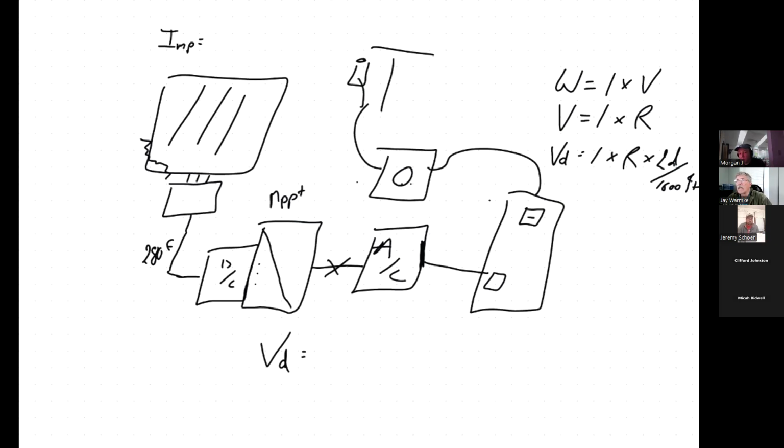And let's say that the panel that I'm using shows me that I have an IMP of 9 amps, and I've got 10 of them hooked together in a string. So in this array, I've got 30 panels. I've got 3 strings of 10. Well, what is the ampacity of one string under this scenario? I'll let you guys answer. If I've got 10 panels, a single panel has an amperage of 9 amps. I've hooked them together in a string, which is a series connection. What's the amps of the string? Oh, it's still 9, right?